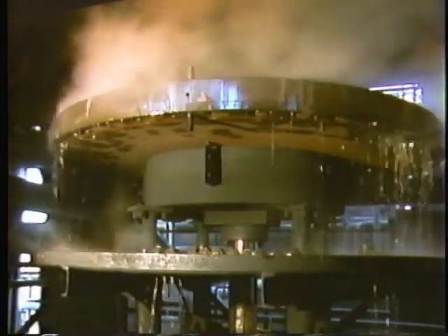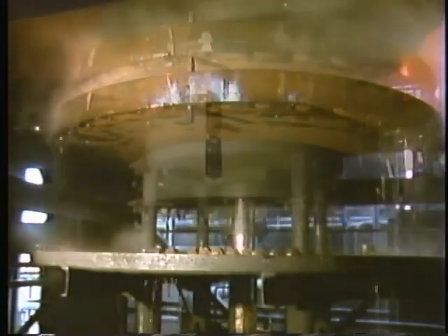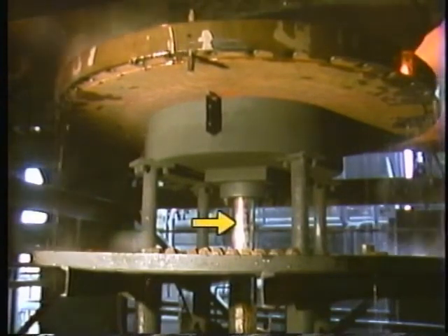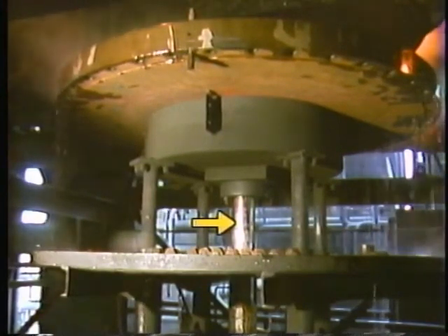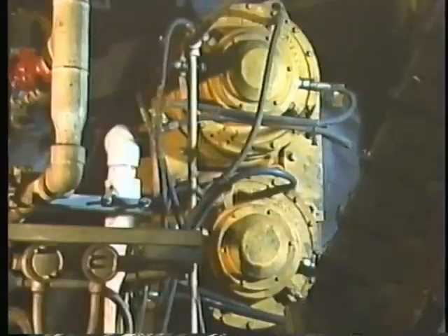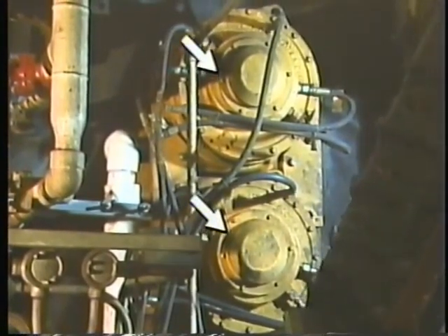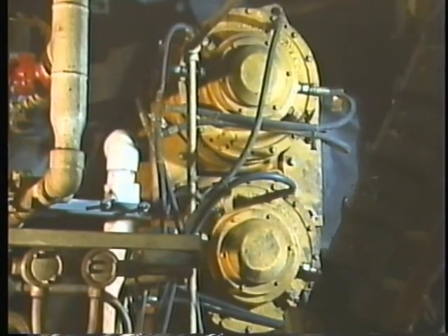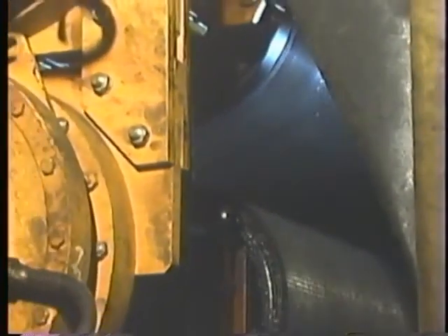In this system, the large force that has to be overcome is a very heavy object, which is raised and lowered with this component, called an actuator. This one is an example of a linear actuator, which means that it produces movement in a straight line. Now, these are different types of devices that also use fluid power to operate equipment. They're called hydraulic motors. However, hydraulic motors produce rotary movement. These particular ones are used to turn the belts on this machine.